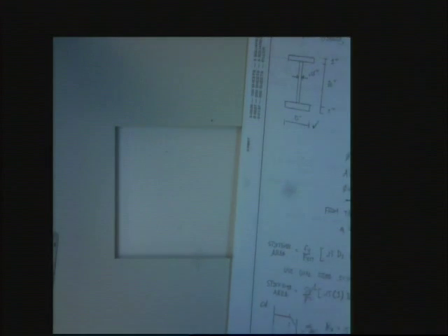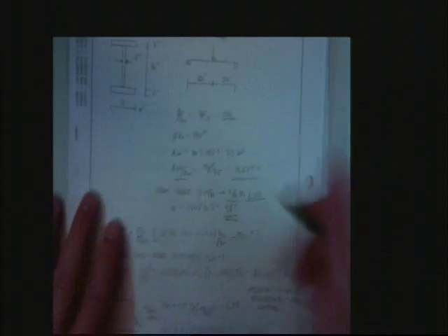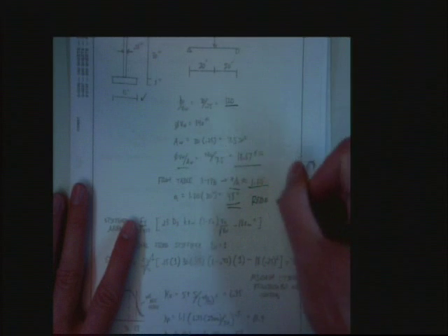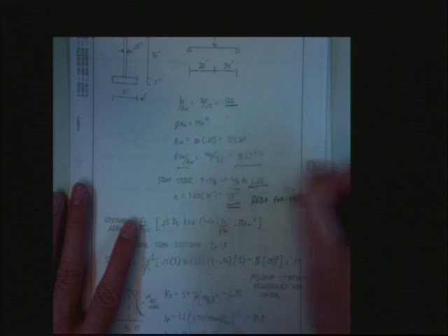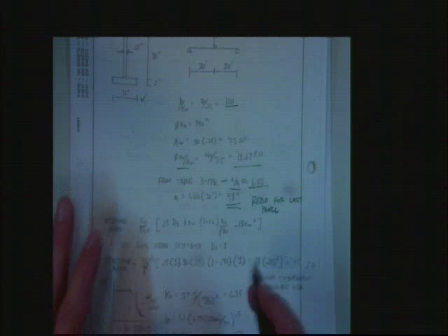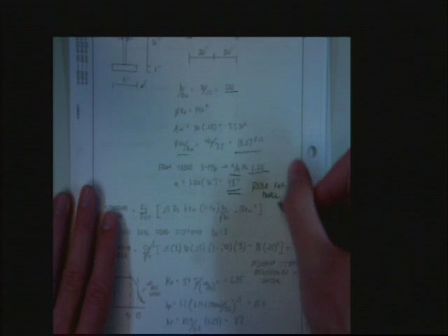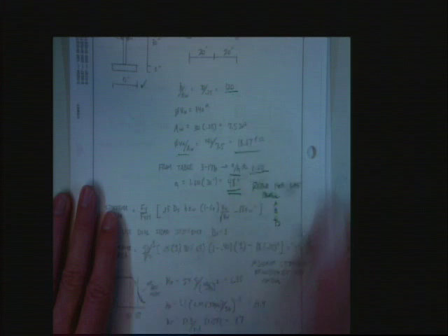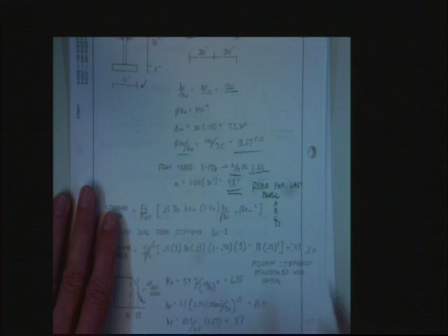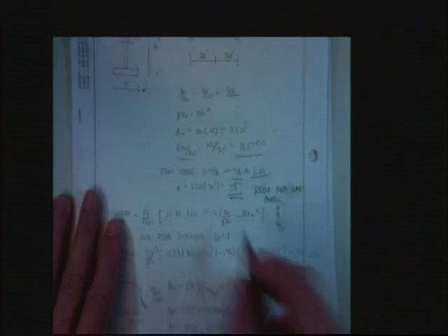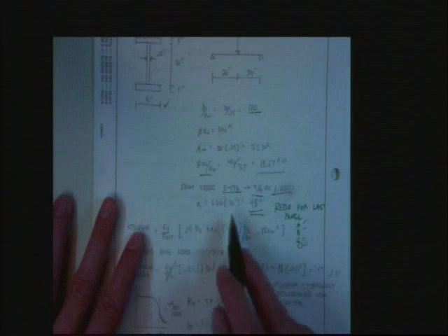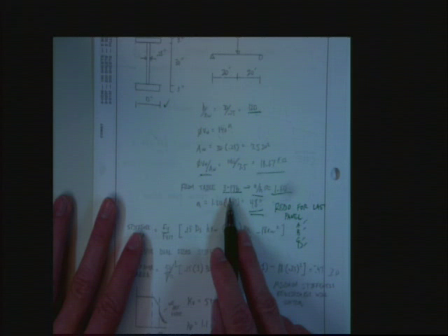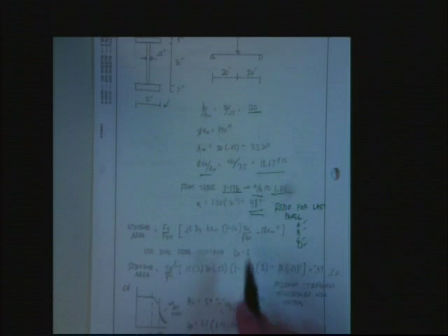Okay. I didn't do that. But you need to on an example problem. So we'll say this: redo for last panel. And it's also possible, actually, I should go ahead and recheck all that rule A, B, C, and D that I showed you, and make sure that I satisfy all 4 of them. Because if I don't, I've already assumed by using 317B that tension field action is going to work. Make sense? Okay. So we keep going.